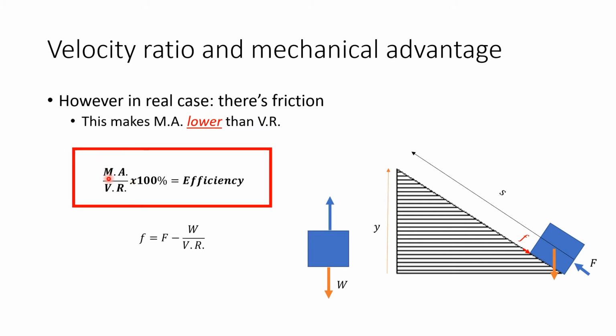since mechanical advantage is the ratio between the forces, you can use this relation to estimate the amount of friction that's being applied to the system, which you would be doing over and over. So from here, you would know the weight of the object that you'll be pushing and the amount of force, which is represented by the mass that you're going to be hanging. And then from there, you could actually calculate the efficiency of the machine and then work on the friction, calculate it, and put it on the table in this lab. Okay.